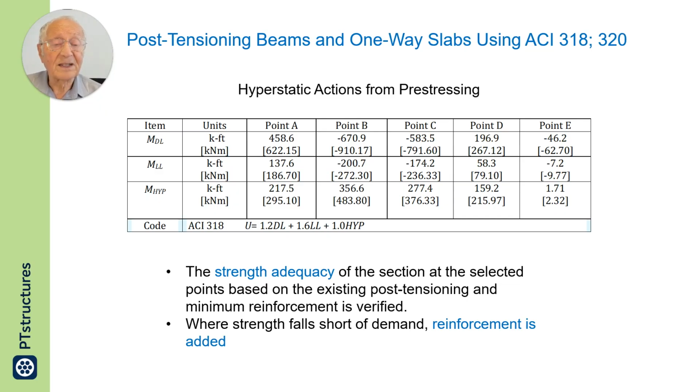Those provide a certain amount of capacity. Let us calculate the capacity and compare it with demand. Where capacity is short of demand, at that location we add rebar. This is much simpler than starting by calculating the required rebar and comparing it with the existing.